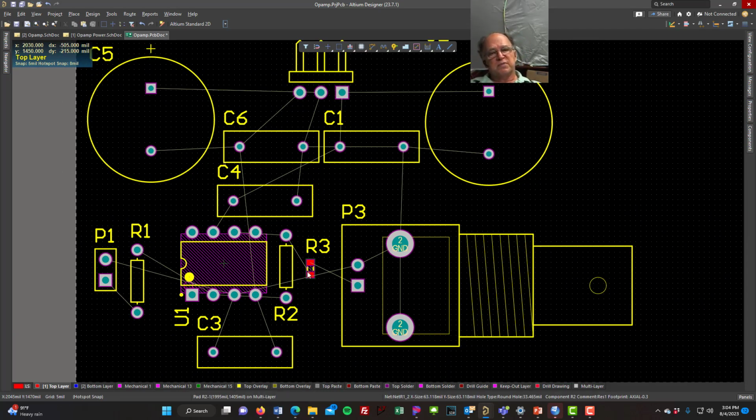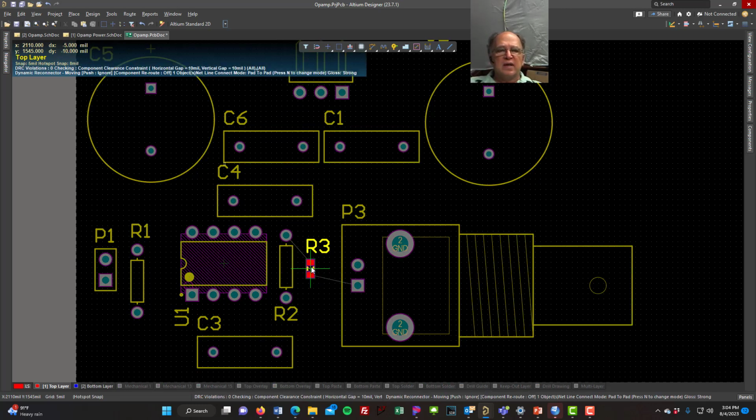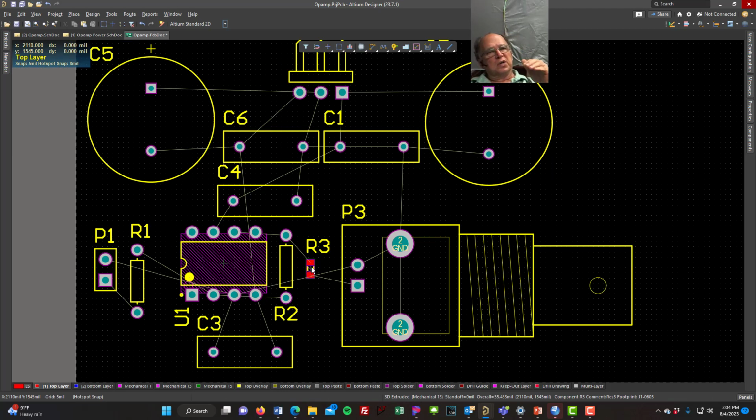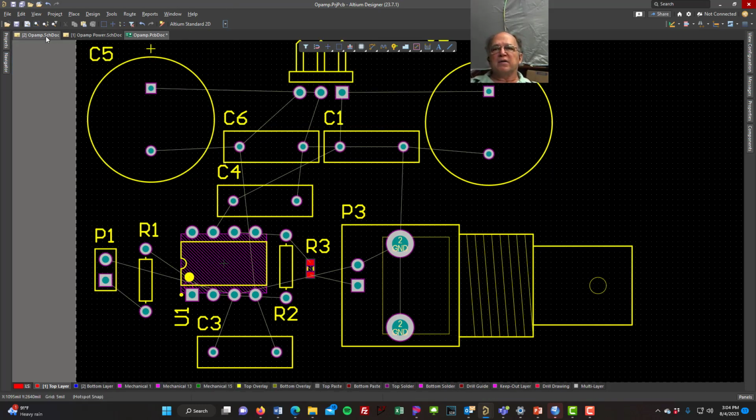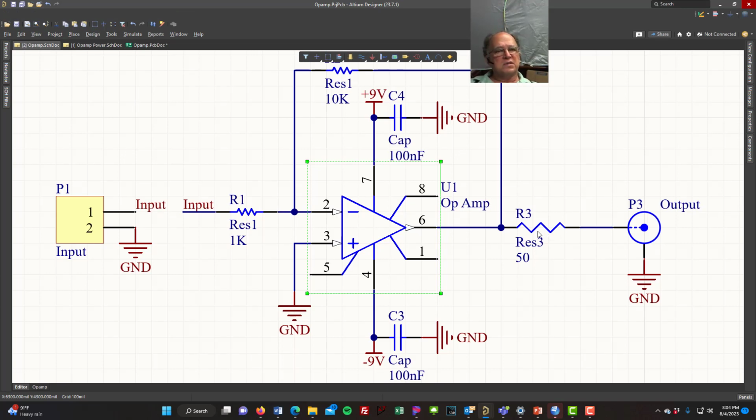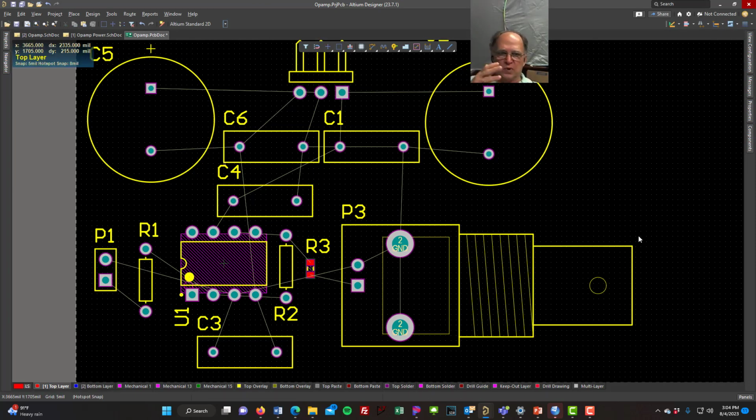So this is called a surface mount resistor. It might actually route a little easier if I did that. This resistor is sitting on the surface, just a little chip. I did that so that we could show different types of footprints, even though it's the same schematic part. I go back over here. It's this guy, right? Same schematic part, resistor, but he has a different footprint. So it's good to see that and understand what's going on. It's like, oh yeah, still a resistor, different shape. They come in all different sizes. So there's my parts.